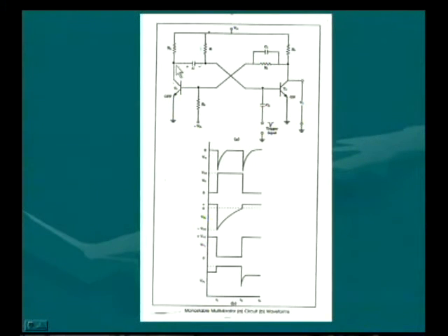As it is in off state, it can be charged to VCC, and the charging current will be the input current to the transistor T2, hence the transistor T2 will be maintained in on state. This state of transistor T1 off and transistor T2 on is continued indefinitely, hence it is a stable state.